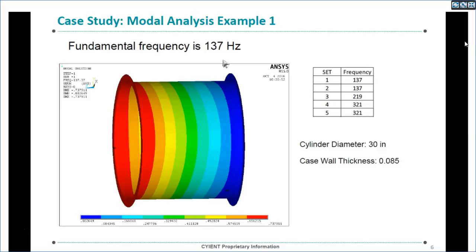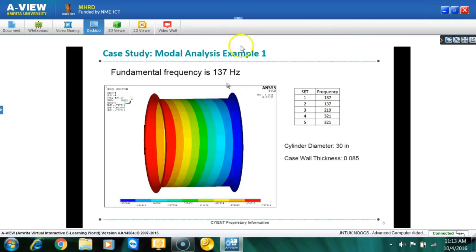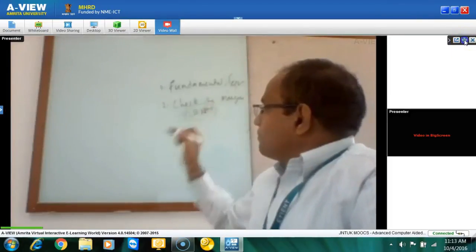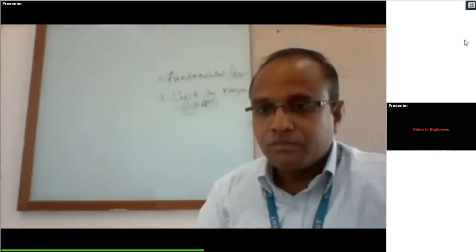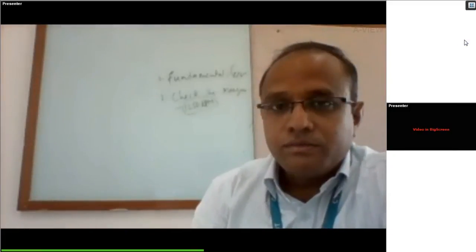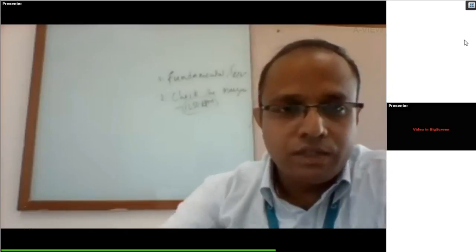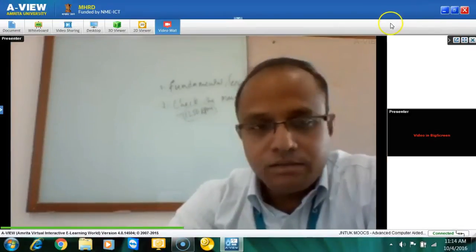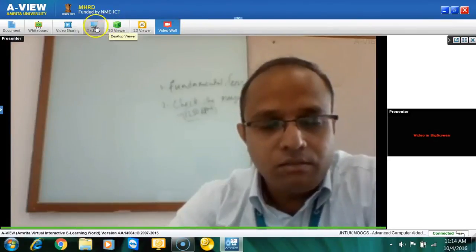The second one is to take the frequency margin from the operating speed. The operating speed is 1250 RPM. So this is the first mode, 137 Hz.